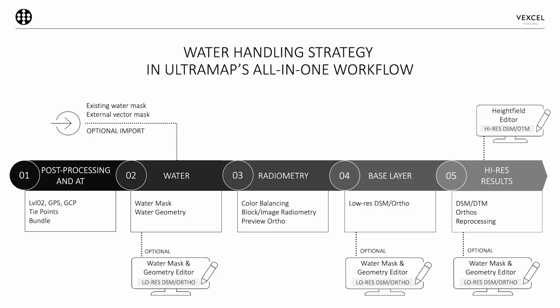On the other hand, high resolution data can be edited as well. We provide the height field editor, which allows you to interact with the DSM and the DTM at full resolution. And for the orthos, we provide a seamline editor to modify the cut lines between the single rectified images for the orthomosaic at full resolution.